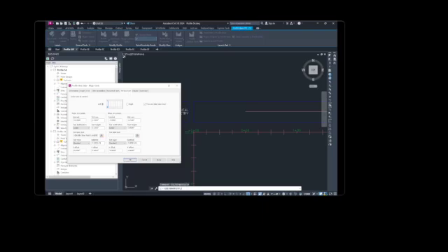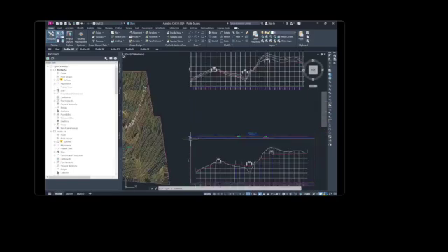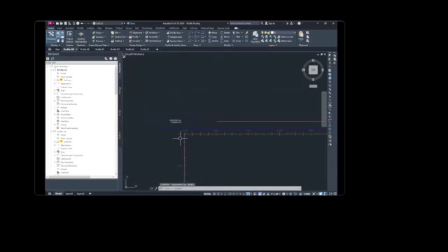On the vertical axis tab, make sure left is selected as the axis to control. In the major tick details, specify the parameters: tick size 0.25, X offset negative 0.1. Click OK. The ticks are longer and the elevation levels move to the left. And then click OK again. These are the ticks longer and the elevation levels move to the left.